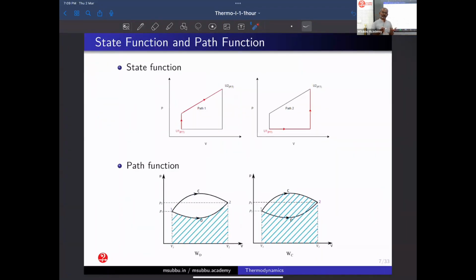Because we know normally this heat, as we used to write, Q equal to mCp delta T or mCv delta T. So when to take Cp and when to take Cv, that again depends on the nature of the process, that we'll see in the aspect of heat separately.